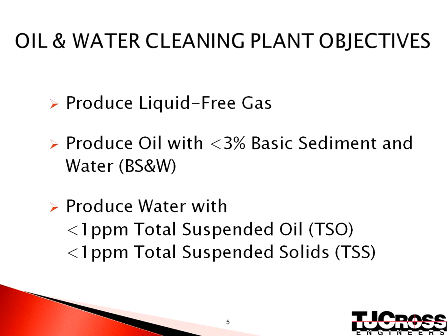Lastly, the produced water must be treated to remove the suspended oil and solids to less than 1 part per million. Produced water can then be further processed for softening, disposal, or injection.